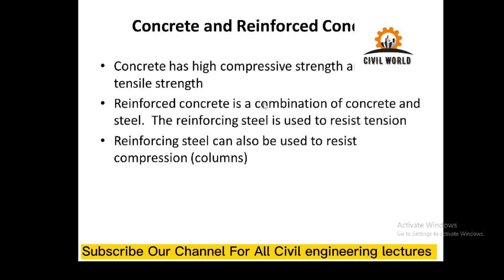However, steel can also be used to take compression in case of columns, or in case of doubly reinforced beams in which steel bars are also added on the compression face of the beams to increase the compression capacity of those members. So we'll be discussing all of them in our course.